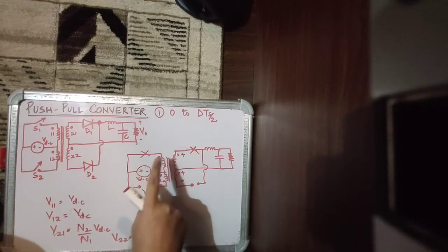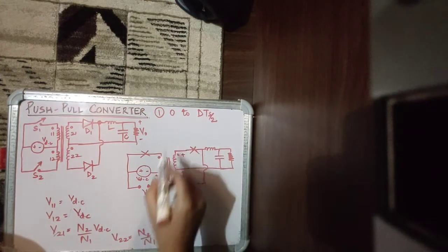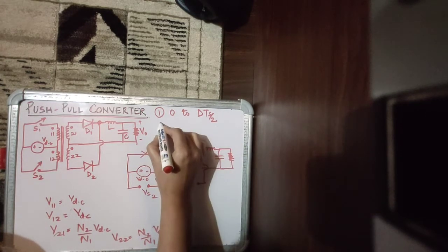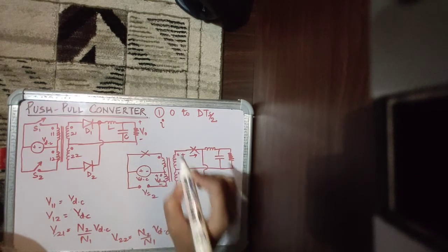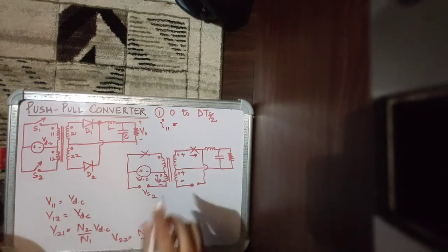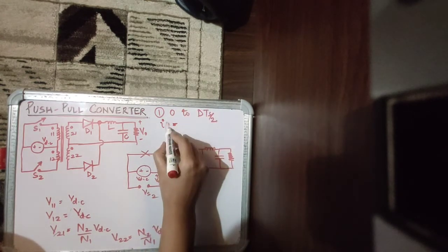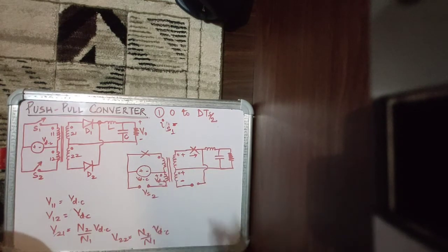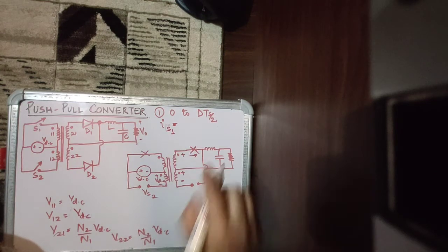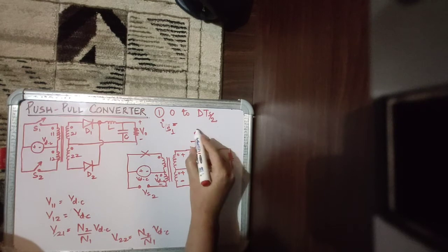And also the primary winding, let's call it I11 over here. So the I11 winding, or you can call it IS1, because S1 is directly connected to the primary winding. So IS1 will carry the load component of current, which is, because this is an open circuit, the inductor current flowing through here.